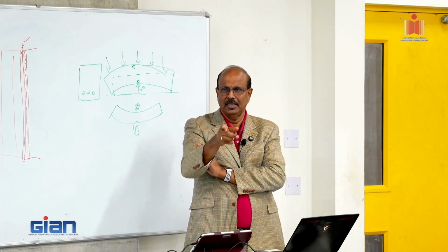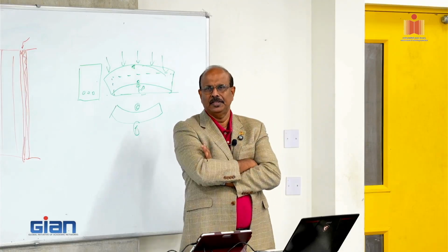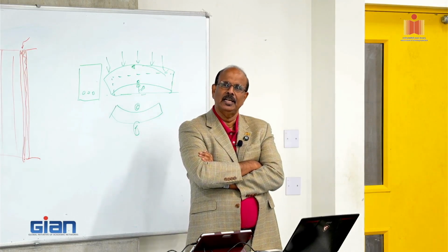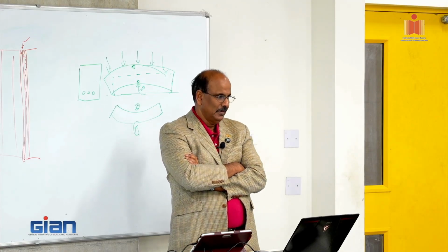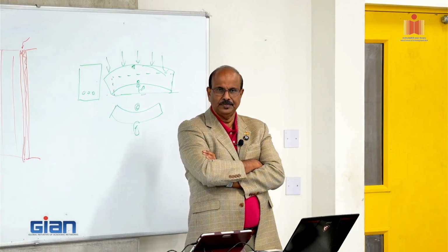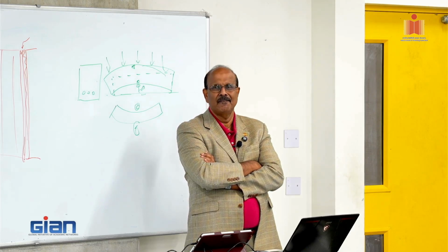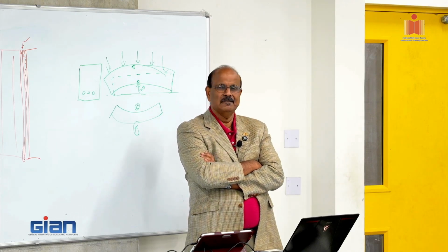Again, one more point. Yeah, I was going to ask. Actually, it will vary based on the condition. Suppose it is a very long span, and I need to control the deflection. Yes, I can have a camber. That's why we decide based on the condition. So you have to play between the stress and the deflection.